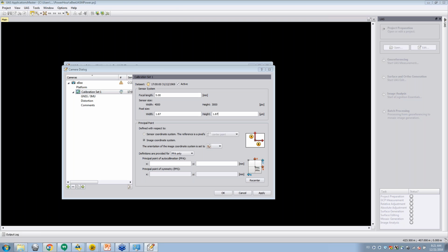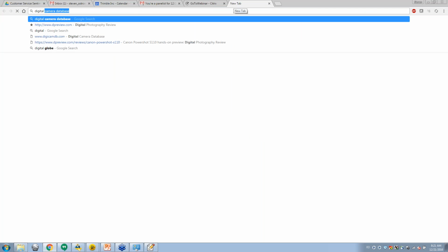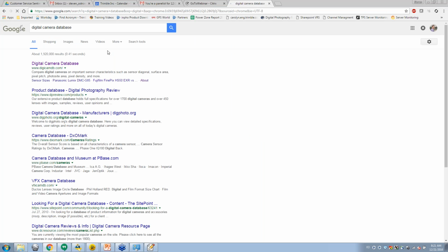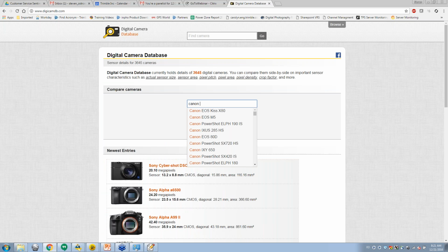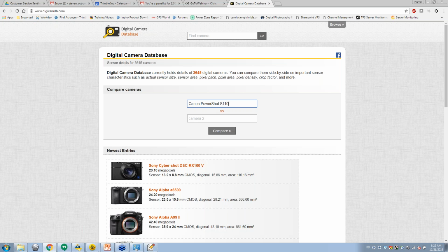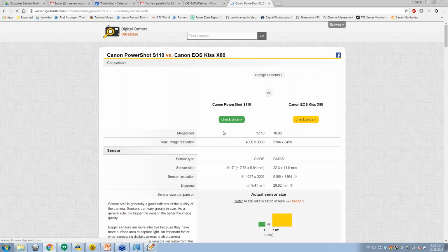The reason we found this was because if you look in the camera manual or online, you can find decent sources. We do not give you these parameters for every different type of camera, simply because they do change. We actually encourage a calibration every time you run a project, because the interior measurements are so small that these parameters will adjust, for example if there's a hard landing or anything of that sort. Can I find most camera models out there on this website? This website is a good source, and I would say essentially for any digital camera, this is a good place to check.